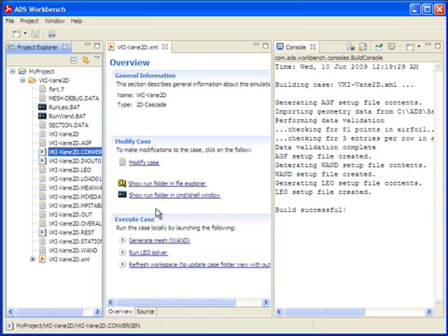Now most of you will likely be using 2D analysis for airfoil design, and that'll include both varying airfoil geometries as well as changing factors like back pressure or flow angles to predict performance across a range of conditions. The good news is that you don't have to go through this process for each iteration. Instead, you can utilize the new from existing capability in the wizard to speed your iterations along. Let's take an example of this.